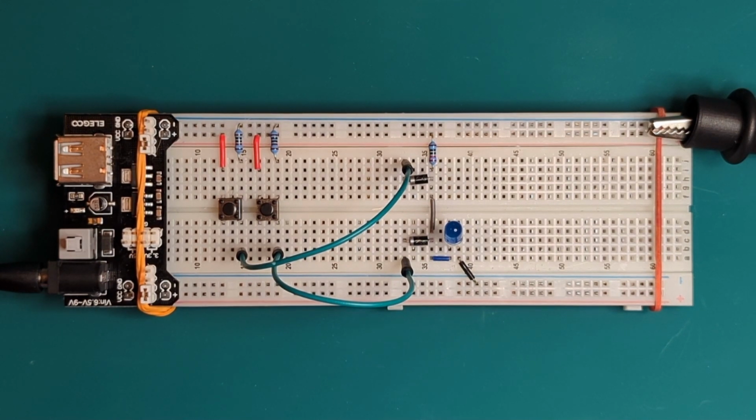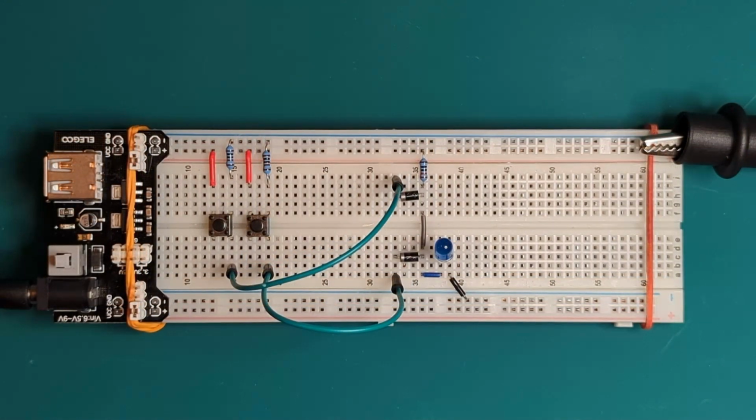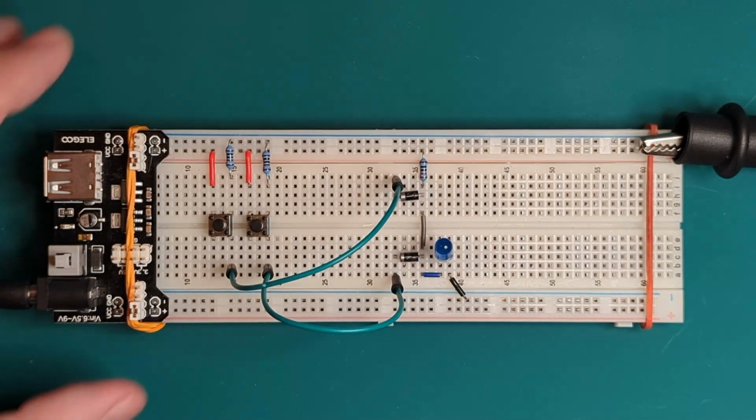What we can do instead is change our button setup. What we need is not to use a pull down resistor. For this kind of push button, I would have to reverse the logic and have a pull up resistor, which means that the button will be high when released and low when pressed. That's the opposite of the usual, unless I change this for a normally closed button, but I don't have any of those. Still, the input values are fine, and we can put back the LEDs to show what's going on. Let's make this change, rebuild the gate, and test.